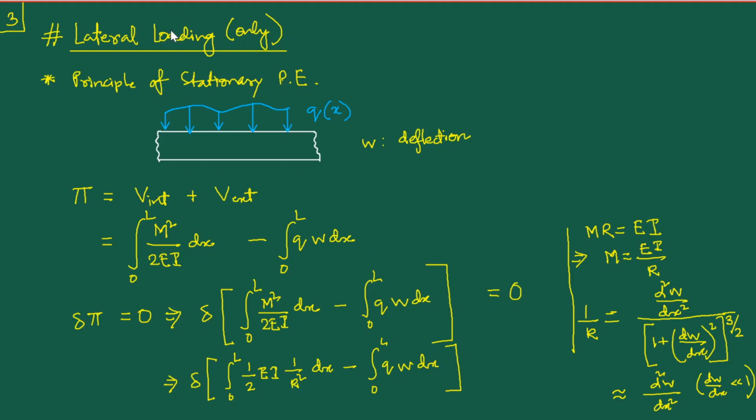But before we do any of that, I want to emphasize something extremely important. You please note that when we are proceeding in this fashion, when we have written down this expression, when we are using these formulae, we are implicitly basing our derivation and our theoretical development on the Euler-Bernoulli beam hypothesis on the one hand, as well as on the linear elastic material behavior on the other hand.